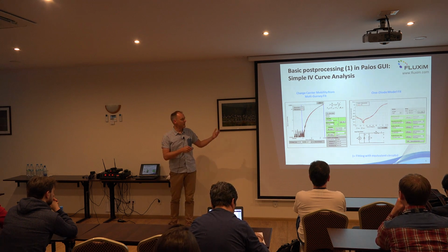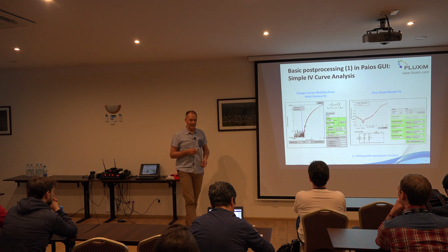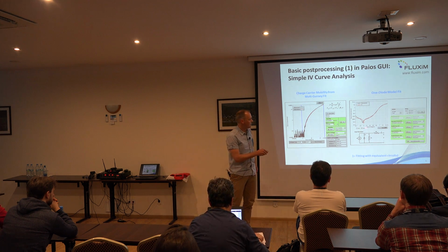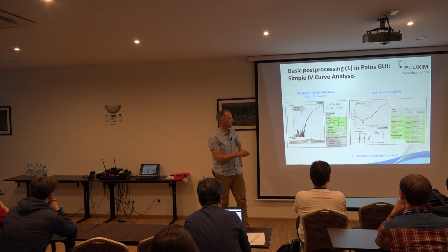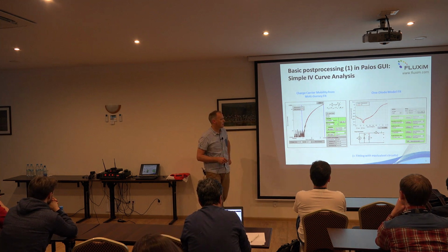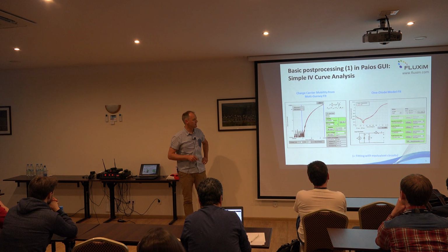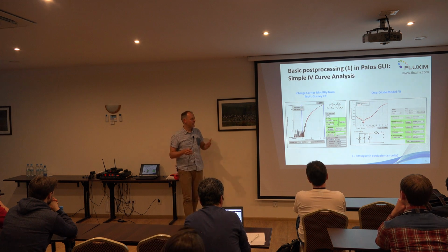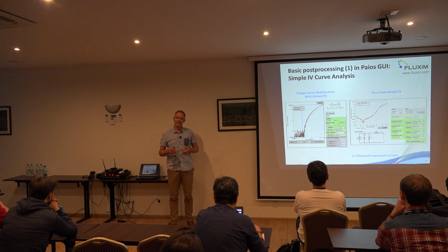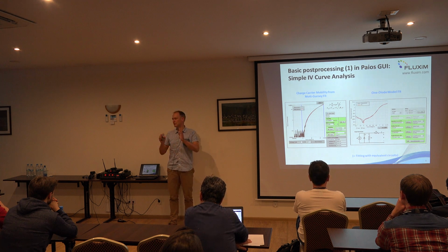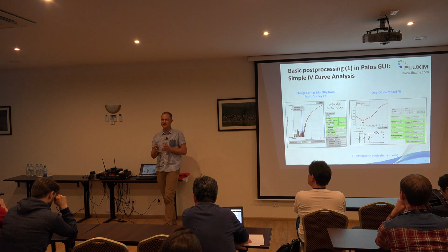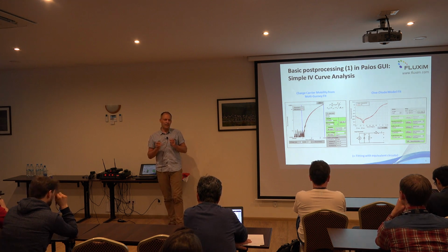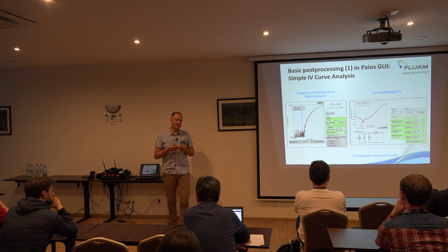But already from this kind of basic post-processing, you can extract, for instance, the series resistance here. Have an idea for series resistance, also for parallel resistance of the device. So there are certain measurement techniques that you just do because you want to know the series resistance. As you know, or maybe I've indicated, the series resistance influences a lot the dynamics of the signal.